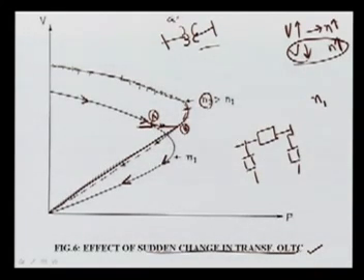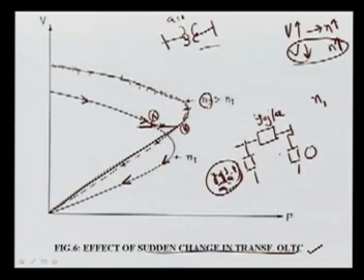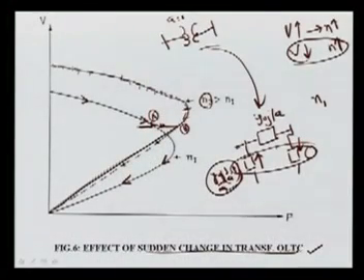If here it is a ratio of A to 1, I can write here the admittance of this as y_ij upon A, and here y_ij times 1 upon A, and 1 upon A minus 1. Here one will be a capacitor, one will be an inductor. So this is effectively just a pi equivalent. What it shows is that one side is providing reactive power just like a capacitor, and one side is absorbing. So again we are going to mismatch the reactive power, meaning somewhere there is injection, but no doubt the total will be 0. So this voltage here is increased, this voltage is decreased, and this is the action of that.